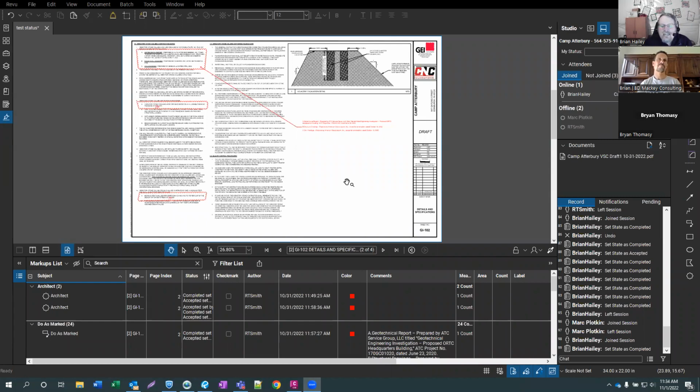So here's what I like to do. I like to use the status for your markups to help you figure out what you've completed and what you haven't. Now, there is the option to change the color of a markup when you change the status. I'm not a real big fan of that, because now it's changing the markup, and maybe we have things color coded for certain people or something like that. Now we're changing the colors, and I'm not a big fan of that. So what I like to do is I like to use filters.